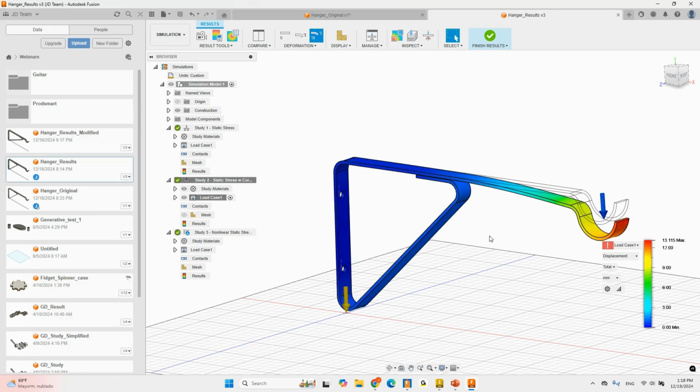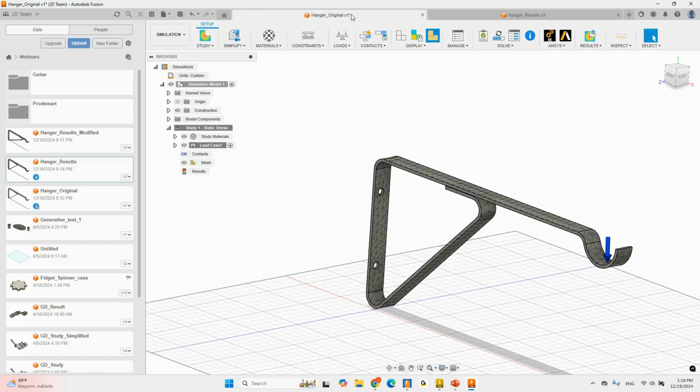And as some of you might know, our linear model for a material is going to be true as long as I have small deformations, right? If I have very large deformations, my material model is no longer accurate. Okay, so I need to specify for large deformations. So probably a good idea would be to run a non-linear analysis with large deformations. So that's basically what I'm going to do here.